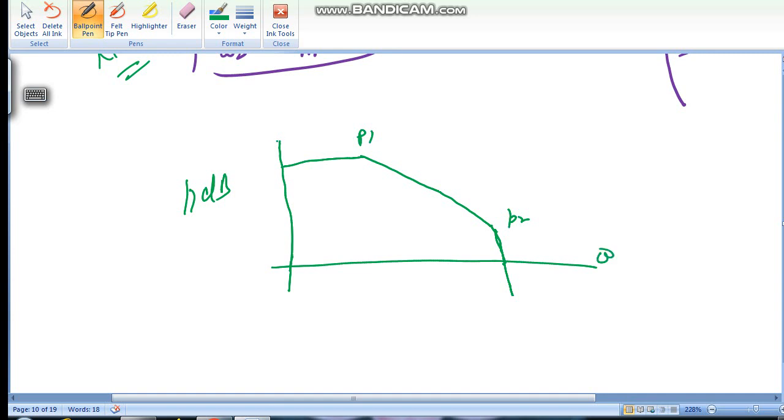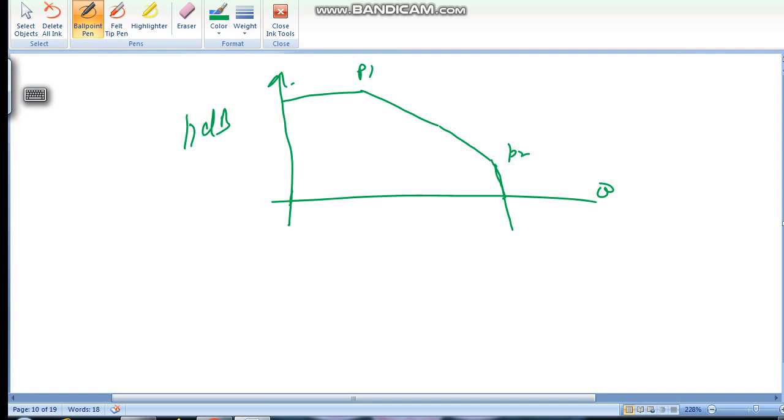Now suppose you are having a zero, and the zero will come somewhere, say here. You put the zero here when you design your circuit. We know a zero will give you plus 20 dB per decade.